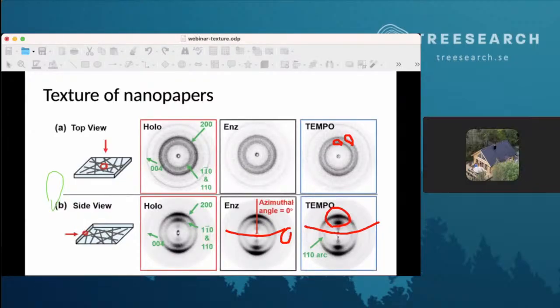Right? Yeah, but the surface energy is the work needed to split the surface, but it's also a measure of how the surface is interacting with other materials. So if you have the surface energy, you can predict the work of adhesion between the surface and water, for instance. But if you say hydrophobic, it's basically 0 or 1. So I'm missing the grayscales.